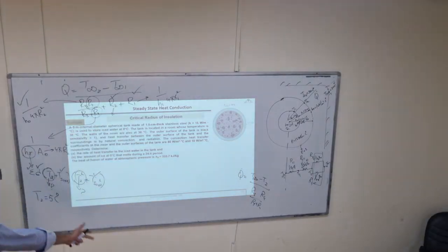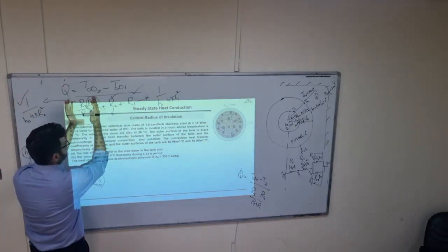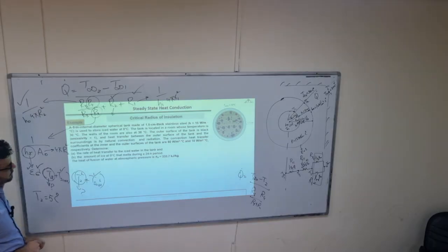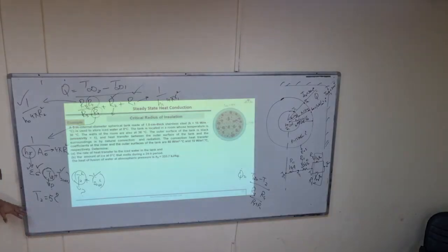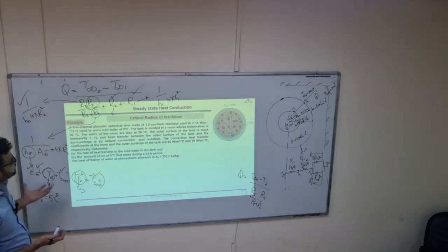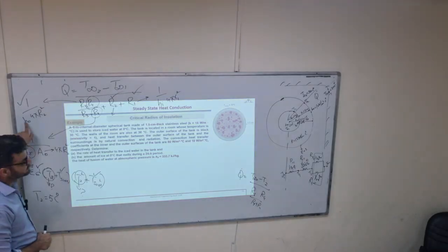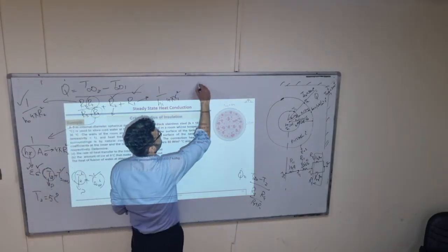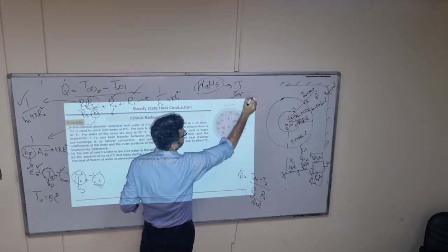So that's how we can solve such problems, because under steady state, the same Q dot is flowing. So we can use this Q dot for the overall system or for a small part. Okay. Any question? This is part A so far. Once T2 is corrected, whatever Q dot you get will be your answer. Now the answer will be in what units? Here we are using watts, watt per meter square. So the answer will be in watts. Watts means joules per second.